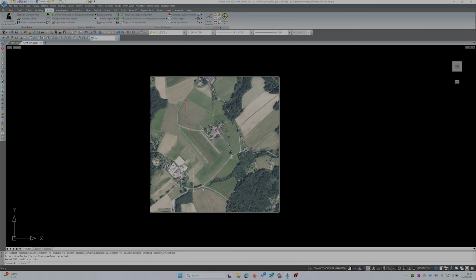Okay, here. Now we want to draw a grid and just do a visual representation on the screen. Okay. It's going to, our profile range is from 0 to station 9. And our elevation range is from 102 basically to 117 meters. We're just going to take the suggestions here for the grid as they are made by the software.